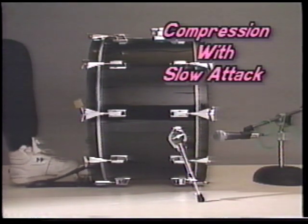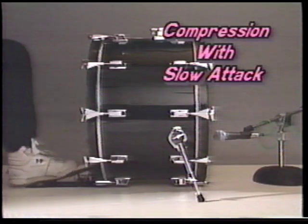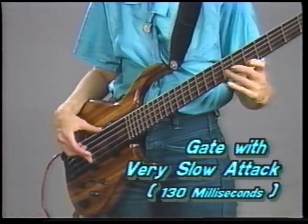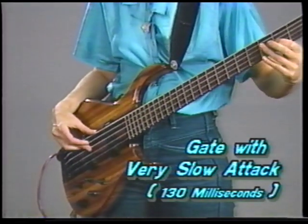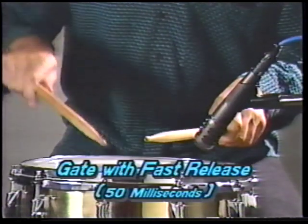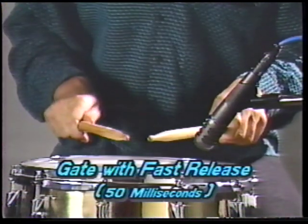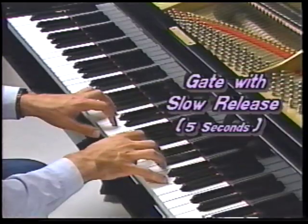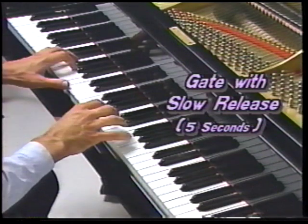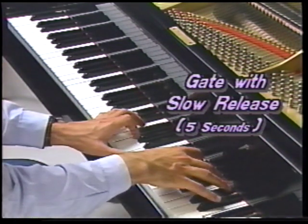Using a slow attack time on a compressor will emphasize the transient or attack of a sound, while a slow attack time on a gate can eliminate the transient completely. Release time determines how quickly a VGA returns to normal gain when the input no longer exceeds the threshold. With both compressors and gates, your setting of release time will depend on the rate of decay of the input signal.